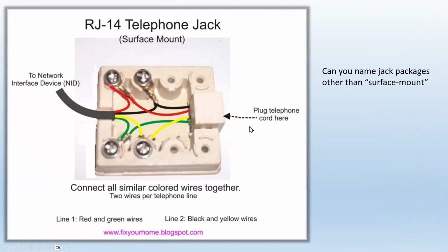Now, polarity matters. However, every phone right now has something that's called a bridge rectifier. I will strongly encourage you, if you haven't studied that yet, study something that's called a bridge rectifier. A bridge rectifier basically turns everything into the polarity that you want. So if you reverse the polarity on one side, it's going to give you the correct polarity on the other side after the bridge rectifier. And that's all I'm going to say about that right now.